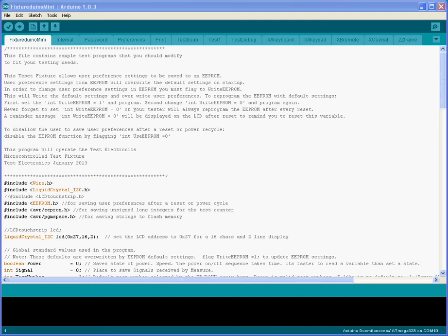The Mega has 8K, but the smaller ones all have 2K, and it was really hard to do all the prompting necessary to run a long series of tests. Because the developers at Arduino came up with a way to store these large static RAM memory hogs, long text strings and character arrays, into flash memory.